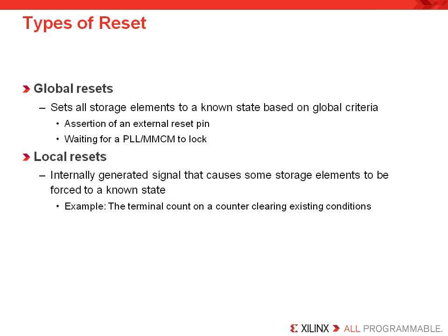And one of the first things to note here is our current Xilinx FPGAs, of course, will offer this feature automatically. So every synchronous element comes up into a known state and defaults to a reset state of 0 unless you program it otherwise. Local resets are internally generated signals that can cause some storage elements to be forced to a known state. So for example, a terminal count on a counter clearing the existing conditions would be a good example of that.